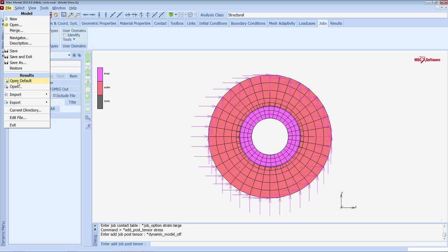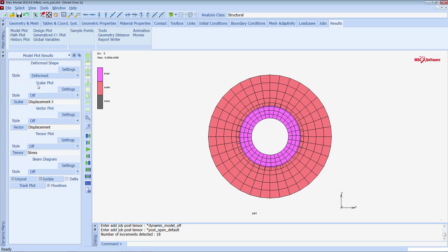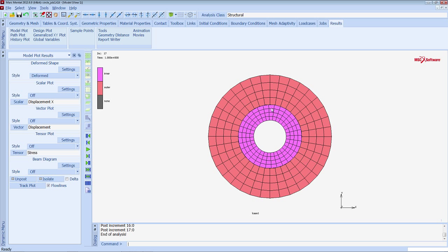So I already have the results file, so I ran this earlier. Again, it doesn't really take much time. It takes just a few seconds. So if we look at it, you see that slowly it resolves the interference. And as it is animating, you might have noticed it seems to be rotating slightly, and that is something you should expect, because I did not really put any constraints on the interior one. So that's the reason it seems to be moving a little bit.